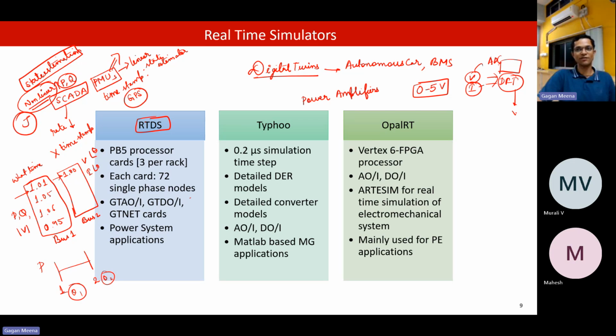Then we find out the voltage and current phasors from that, and it can continue tracking them. There are different algorithms for fault detection based upon these phasors. Once the relay senses that there is a fault, it can issue a trigger signal, and this trigger signal is a control signal.